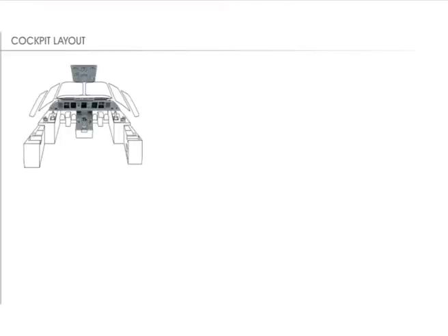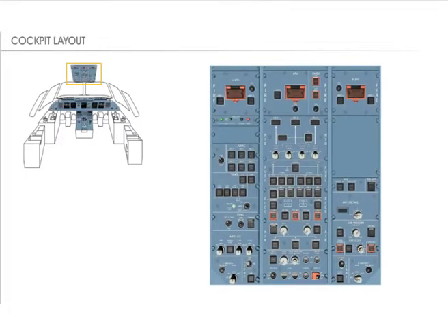The controls of most aircraft systems are located on the overhead panel. For example, fuel, air, hydraulic, electric, fire. The overhead panel is organized with the main system controls located in the center of the overhead, and the most frequently used controls located at the lower section, forward, within easy reach of the flight crew.